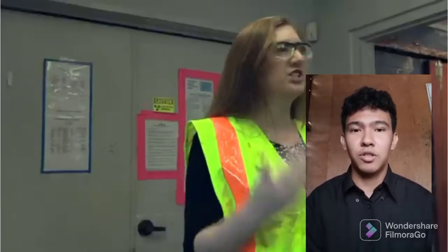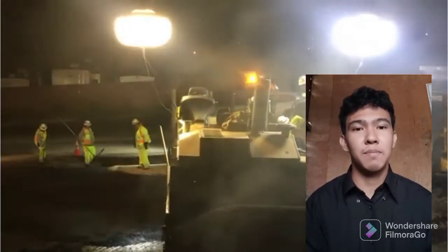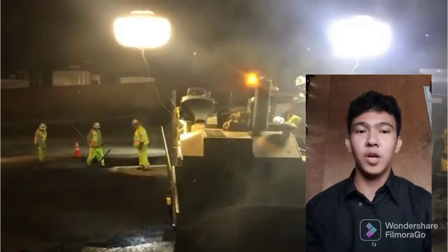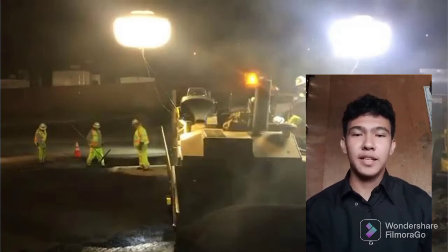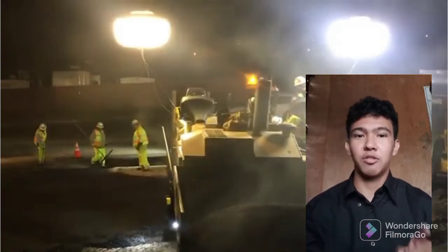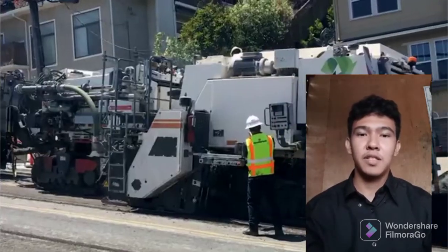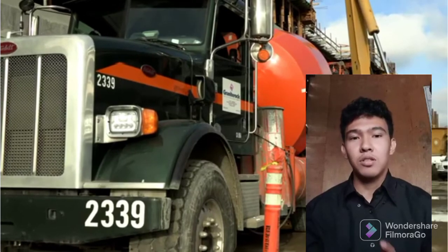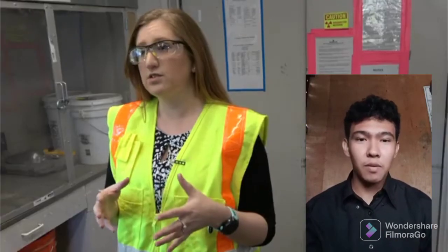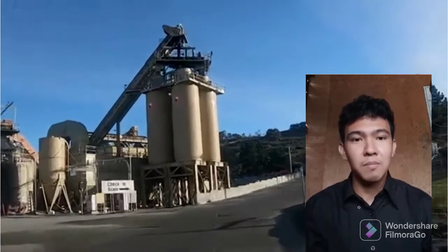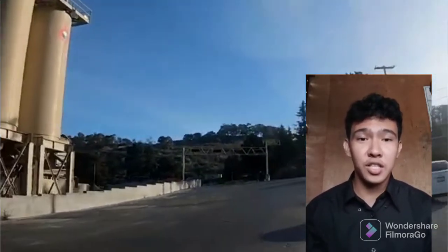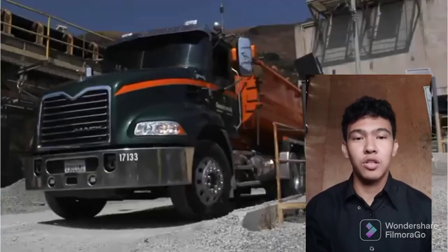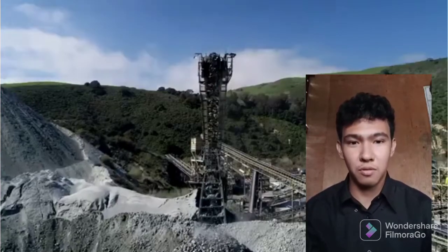After a road surface has been put in place, a series of quality tests must be performed before the road construction project can be deemed complete. This procedure involves checking to confirm drainage, grading levels, and other aspects of the road are satisfactory. Once all the checks return positive results, the road can now be opened for use by motorists. Most roads can last up to 40 years, with major upgrade works due every decade or so.